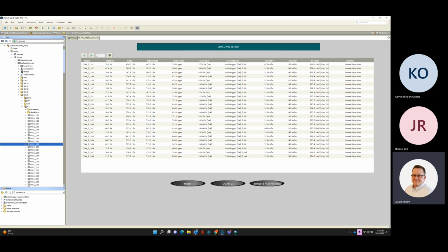With that being said, we switched from our Fancoil graphic to our VAV mode, and we were looking at VAV 202 from our Fancoil, right? So you can see we put pertinent data up here: damper position, airflow, effective airflow set point, space CO2. You can see the CO2 load. You can see the CO2 set point. You can see the max airflow set point, min airflow set point.